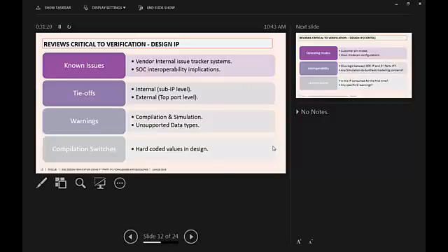Your linting tool is also very capable of finding unconnected ports, which, if you don't pay attention, will be problematic when you want to upgrade this IP, or ask the vendor to support something. They may say that's not possible, and you need to understand that these data types are not supported. Also, the simulation warnings and linting may include some related to the configuration. Yeah, those are the issues.